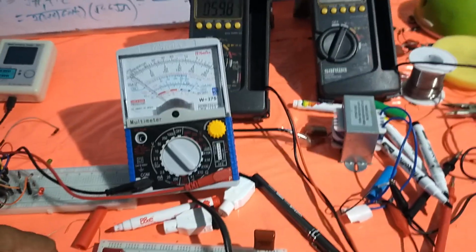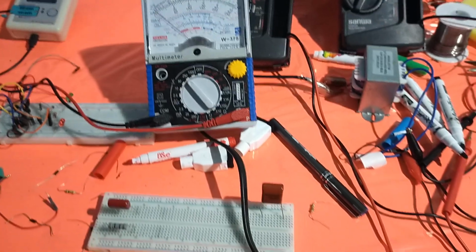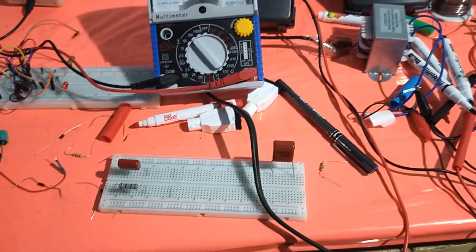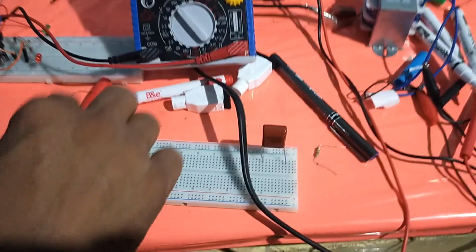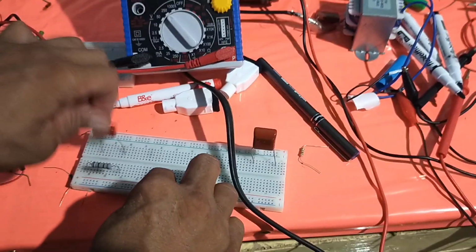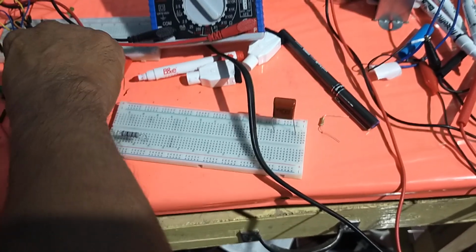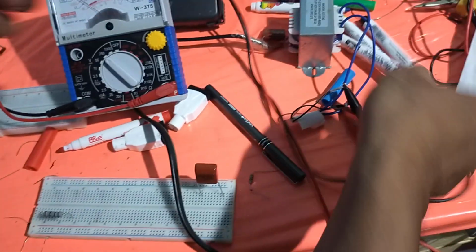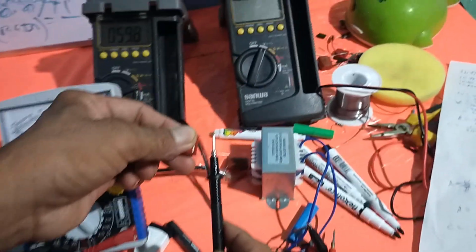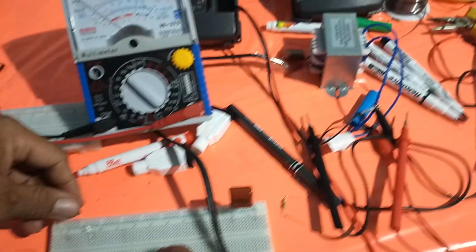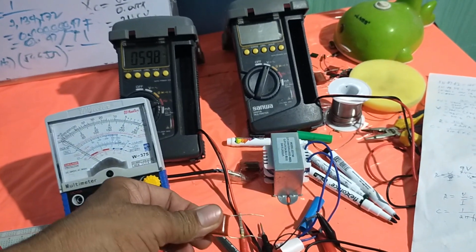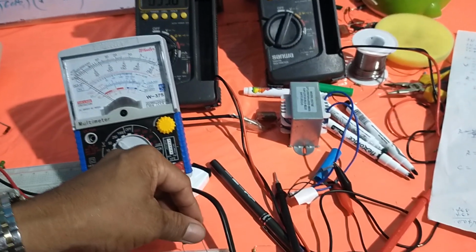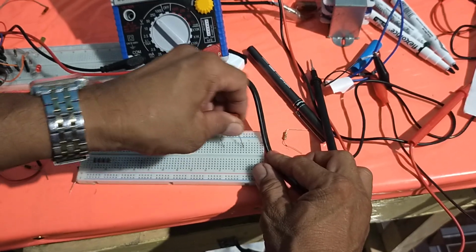That is why there is a necessary procedure to stay away from the risk. So let us first short it if there is a remaining voltage here, or over here. See? There's still a remaining voltage in this capacitor.